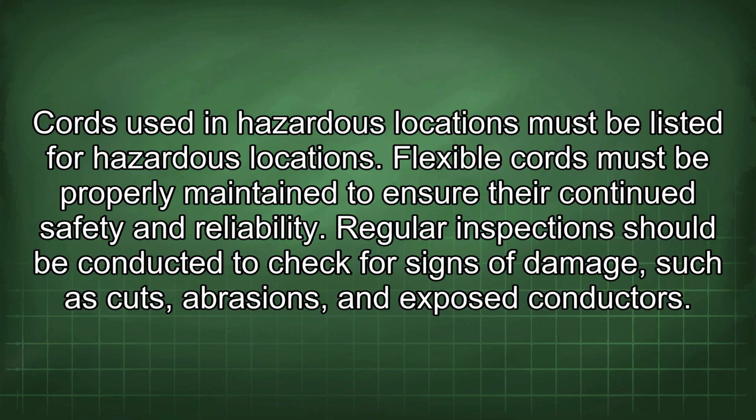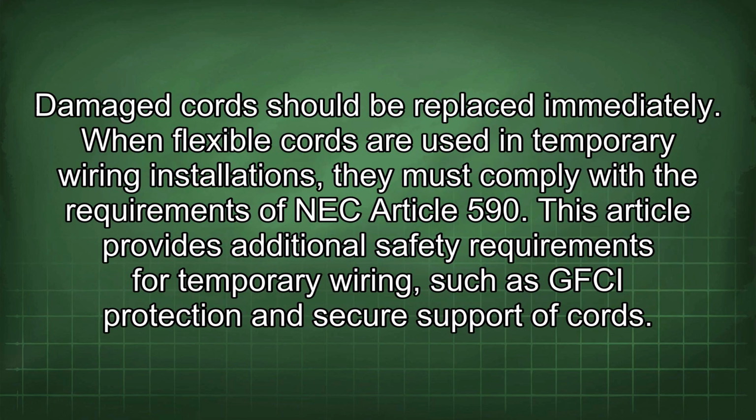Flexible cords must be properly maintained to ensure their continued safety and reliability. Regular inspections should be conducted to check for signs of damage such as cuts, abrasions, and exposed conductors. Damaged cords should be replaced immediately.